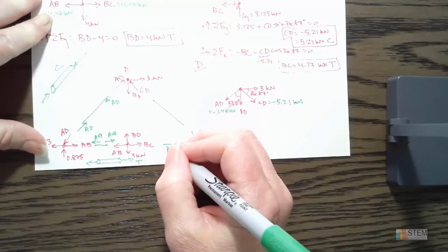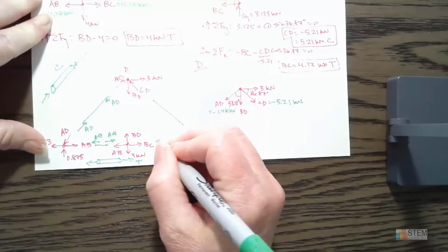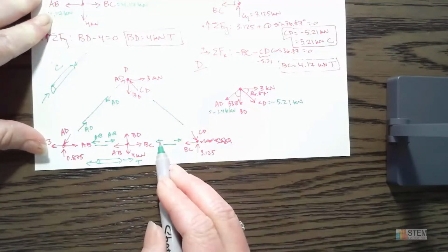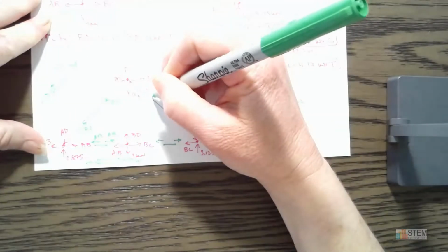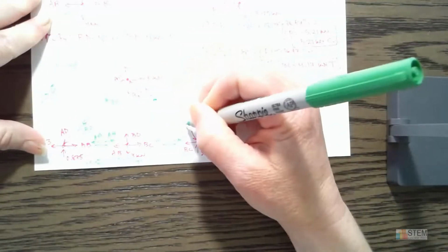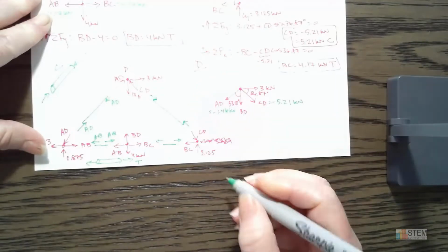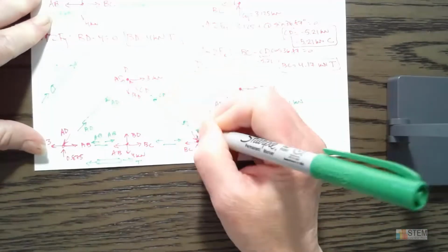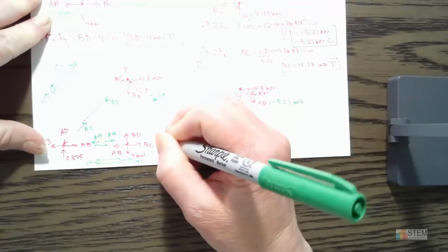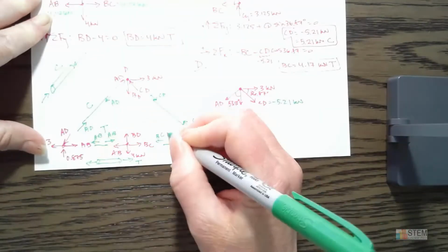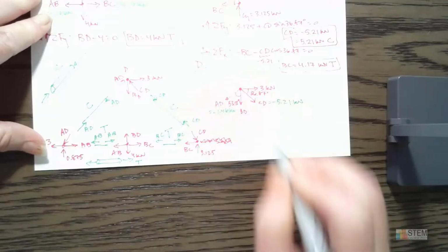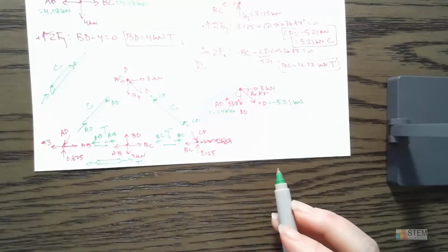And you can go through and keep doing the same things for these. So opposite directions, and then here you want opposite directions, so we'd have forces going into the member. All right, and these are CD, these are BC. Okay, so this one's compression, this one's tension, this one's tension, this one is compression.